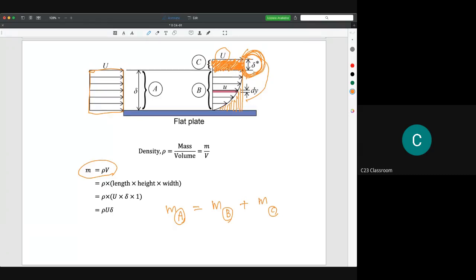The displacement thickness of the boundary layer is 100% imaginary thickness. We cannot measure it through experiment with any device because the displacement thickness actually does not exist. The idea is to make sure that our equation fulfills the conservation of mass. That is the purpose of this calculation. The only thickness that can be proved in experimental work is the boundary layer thickness only, the delta. However, the equation for delta is quite simple and straightforward. It's just the value of y.